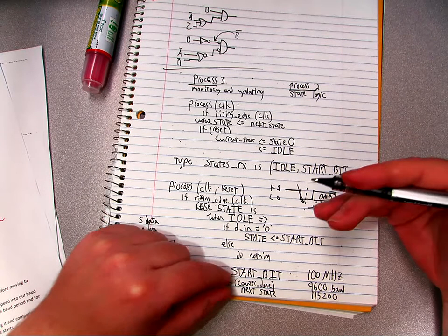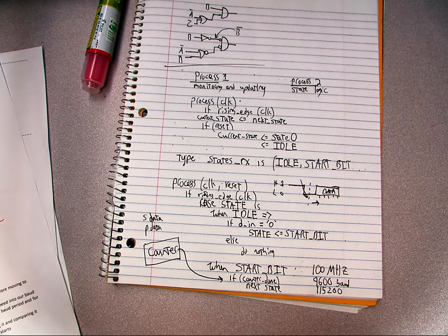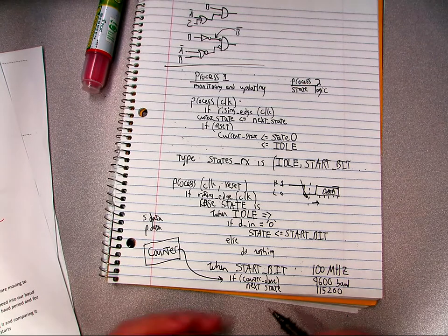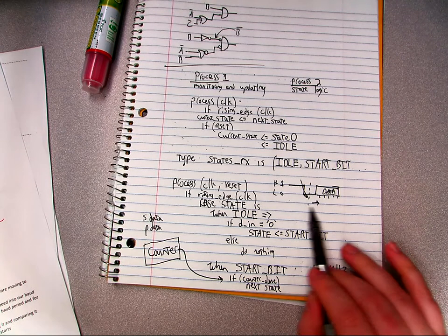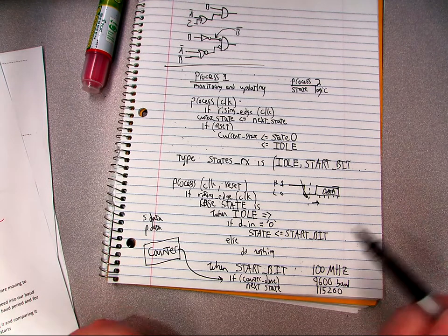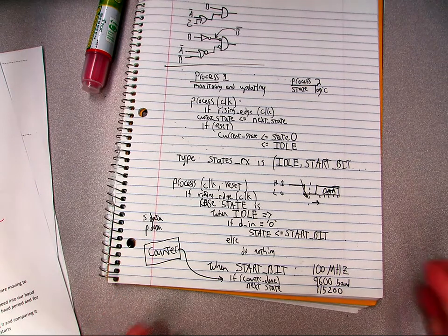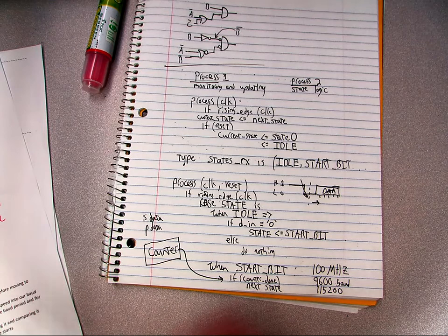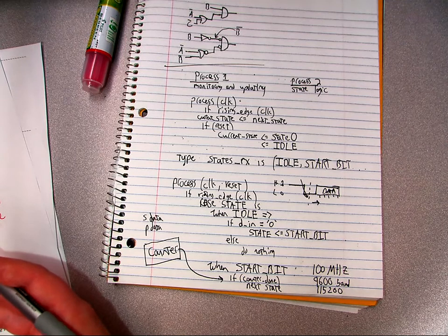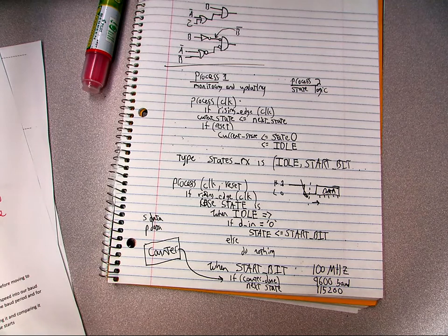Your data bit, which is going to come after start, which is where I'm going to leave you guys off to puzzle it out mostly on your own, the data bit has to count 2 things. It has to count both the time between bits, but also how many bits it saved. Because it does need to save data in, right? The S data. So you need to save the data, count how many you've saved, and come up with some mechanism for knowing when to move on to the save data state or the stop bit state, really. So hopefully that's enough of a clue on how to design that.